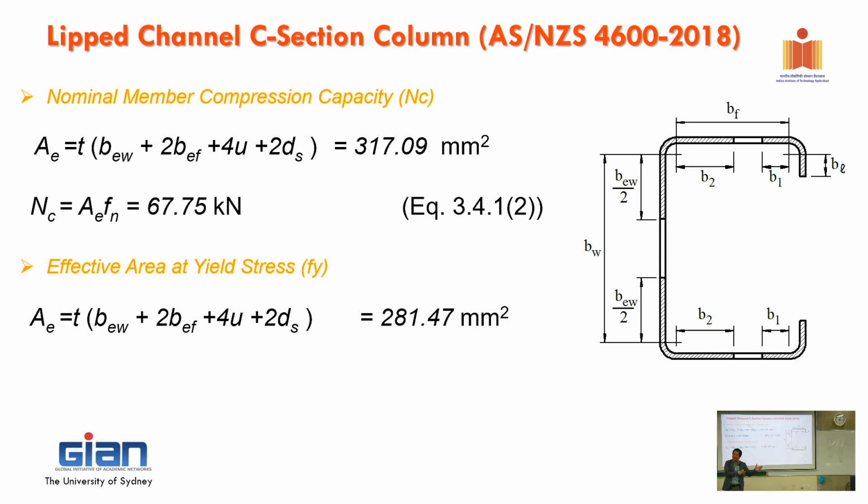So what he did here, he's trying to calculate the buckling, the member capacity, to take into account all the interaction as well. So the reason you have Fn smaller than Fy is because you got a bit of interaction between local buckling and a bit of flexural-torsional buckling and everything there. So that's why it dropped down the buckling stress. Okay, so a little bit complicated. What you're asking is really good.